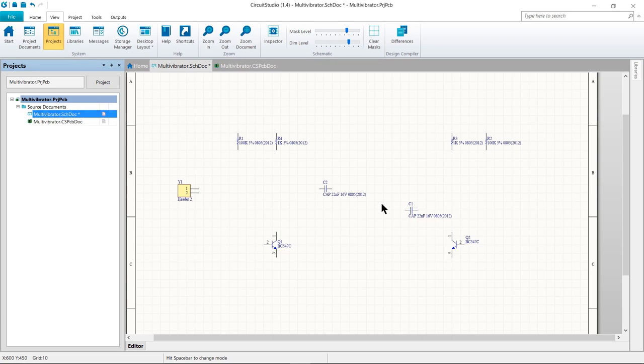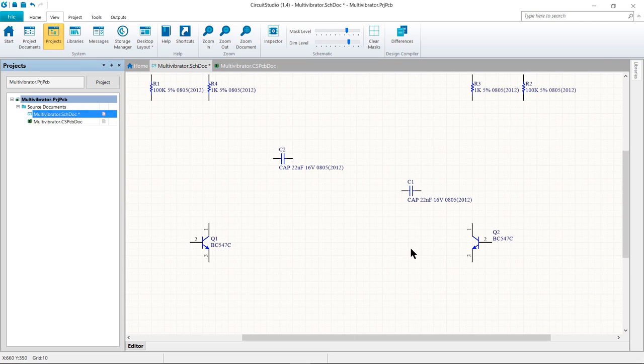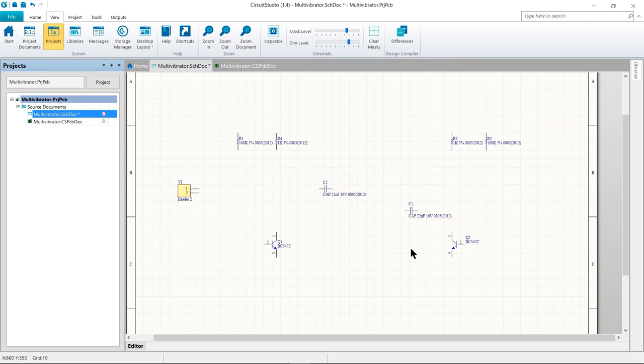So wiring is the process of creating connectivity between the various components of your circuit. To wire up your schematic, again, refer to the schematic diagram and go ahead and complete the following steps, or just go ahead and follow along with me. Again, to make sure you have a good view of the schematic sheet, you can press Page Up or Page Down to zoom in and out.